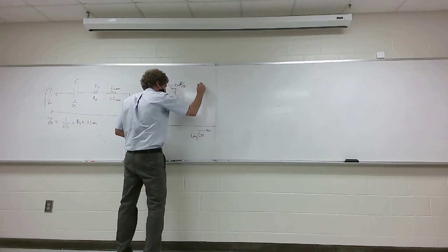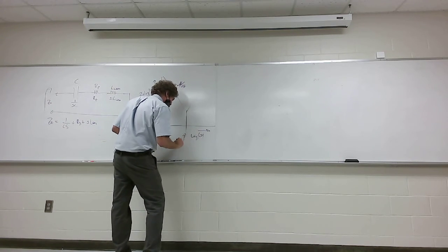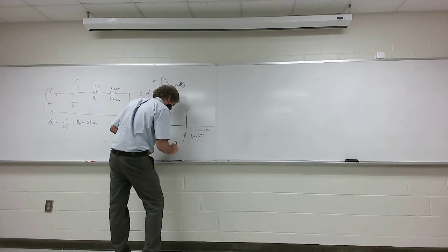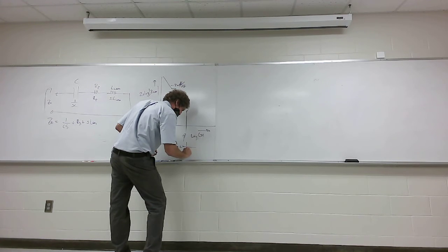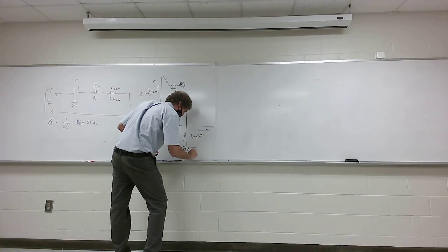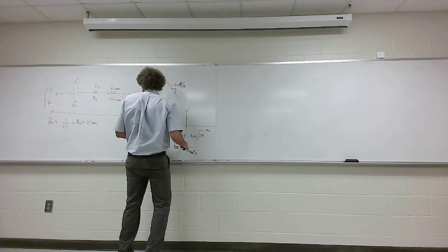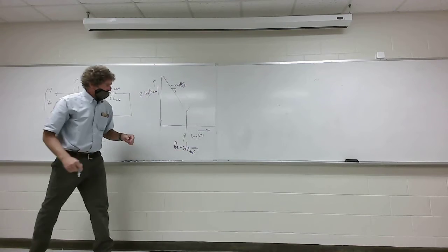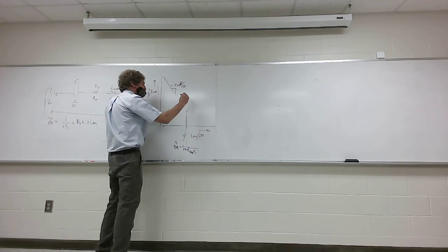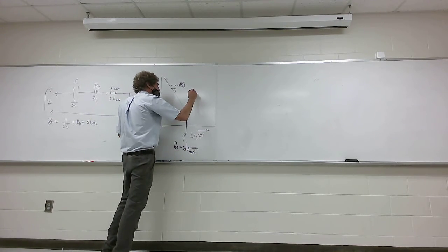But here's the thing. The self-resonance right here, f self-resonance, is the only thing you need to know. And that's 1 over 2 pi square root of L, and that's L parasitic, or L lead, it's unwanted, times C parasitic, or actually C period, it is the C. And so the self-resonant frequency is the only thing you care about. And then it starts going up at 20 dB per decade.